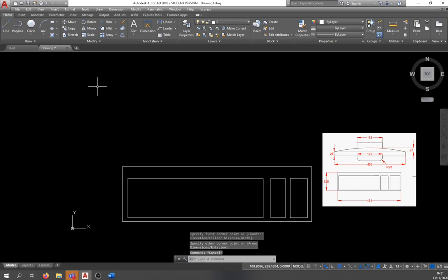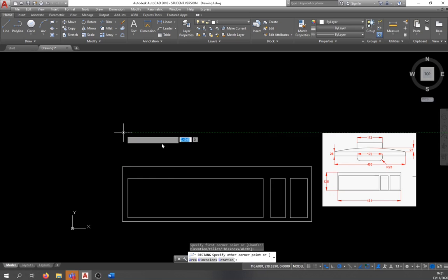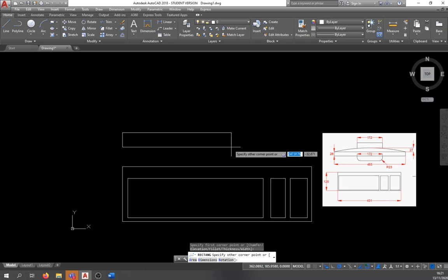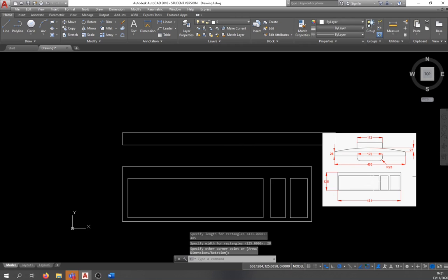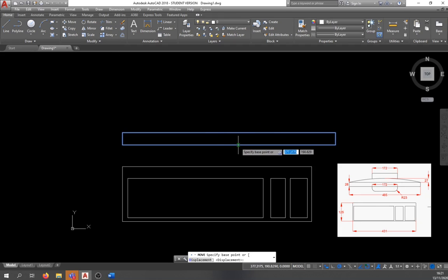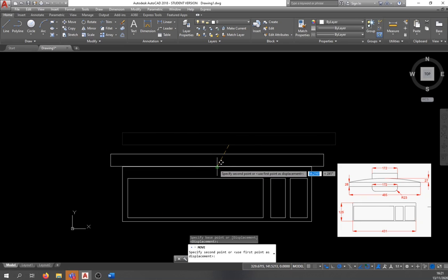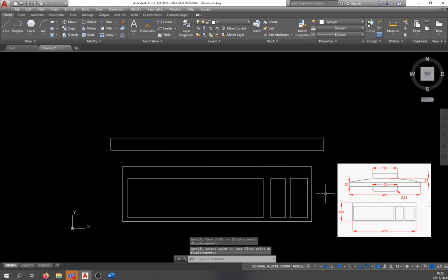So there we go. Now to draw the monitor, it's another rectangle, 485 by 28. So dimensions 485, 28. Okay, I need to move this a little bit. To make it look nice, I want to center the monitor. I have my object snap here for the center line, which is a little triangle. If I match up to the center line of the keyboard, hover over it, and go up a little bit, there we go, that's centered the keyboard and the monitor over each other.